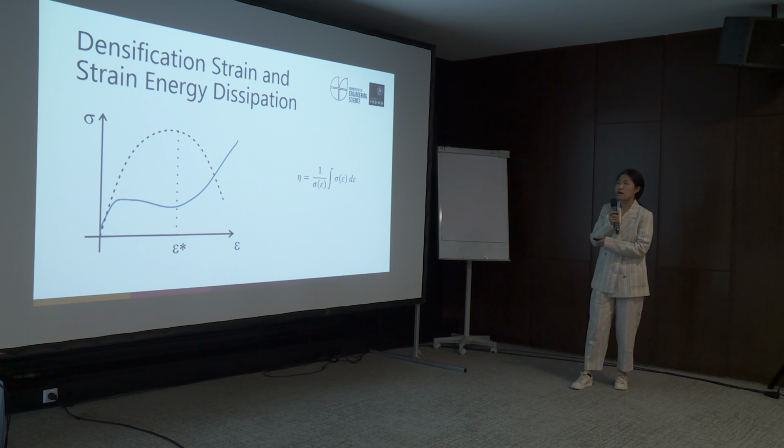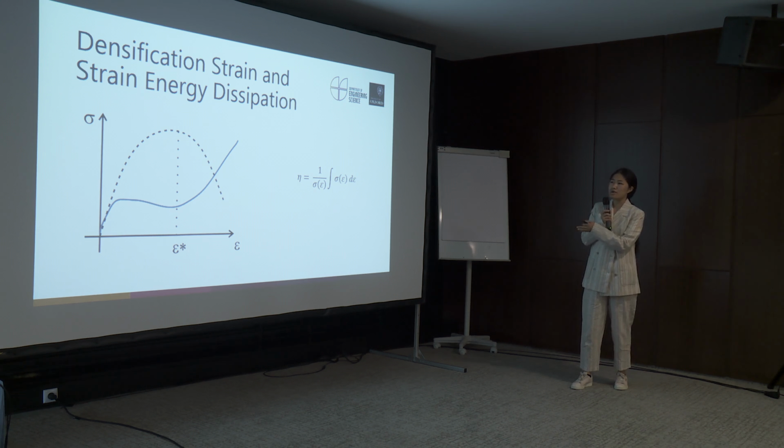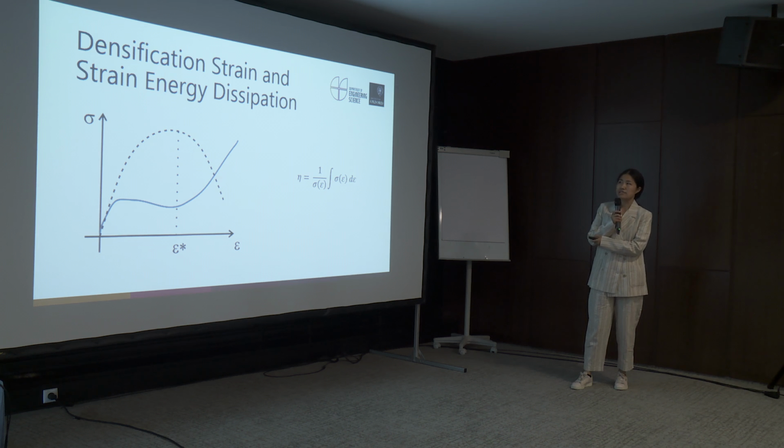Here we use strain energy dissipation efficiency curves to define the densification strain. The strain at which the efficiency is maximum is where densification occurs, which gives a unique and constant result.